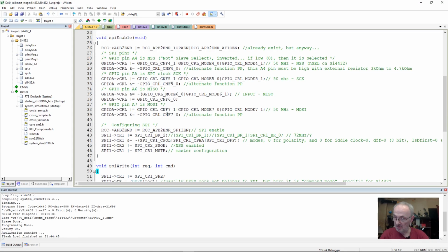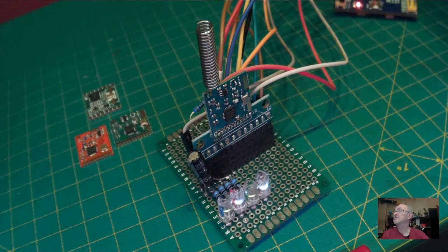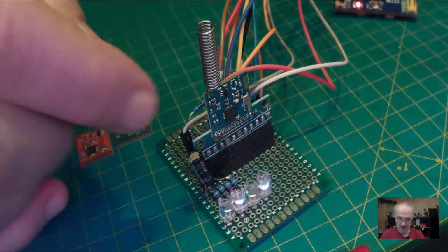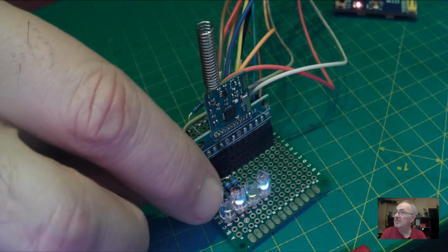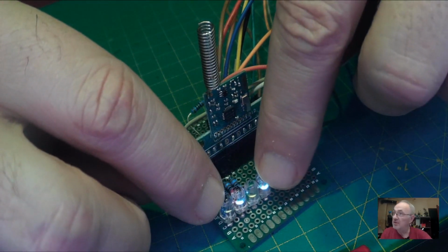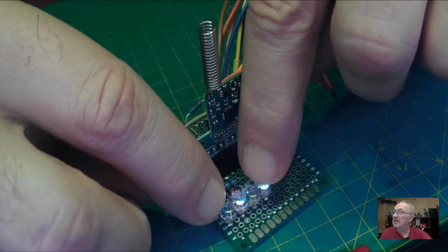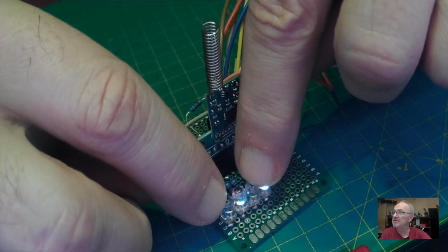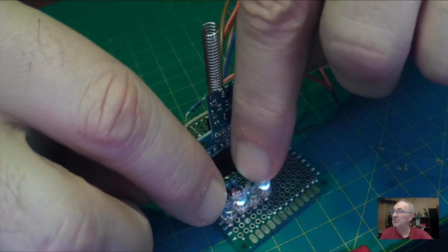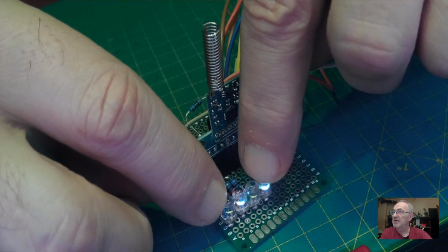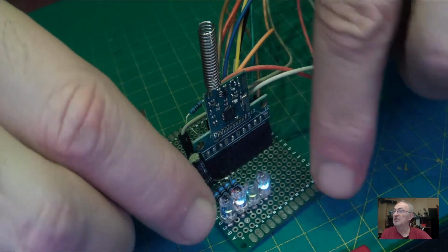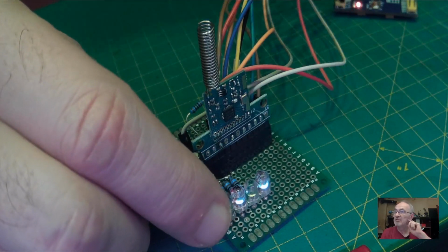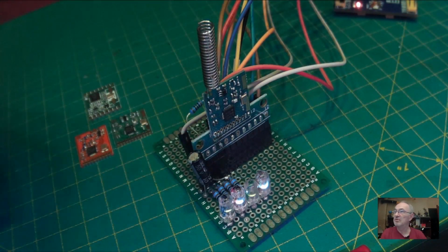So now let me show this module. When I start, I have some control LEDs: this one lights when receiving, this one when transmitting, this one is power on, and this one is not working. There is a generator inside. You can get 32.768 kilohertz for clock purposes, or 1 megahertz to 10 megahertz, up to 30 megahertz. This is made because you can use this clock to power a cheap, small microcontroller up to 30 megahertz, instead of having a separate clock on the microcontroller.